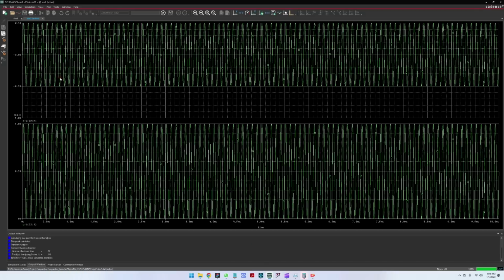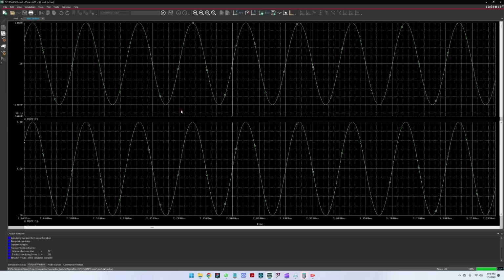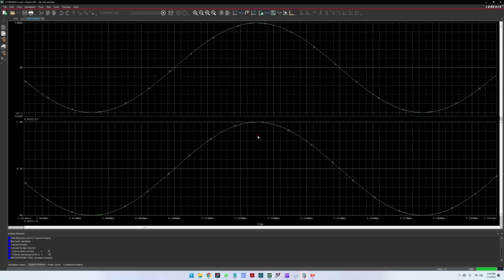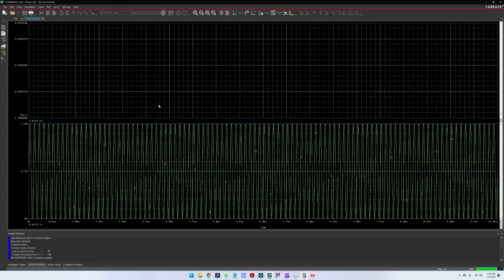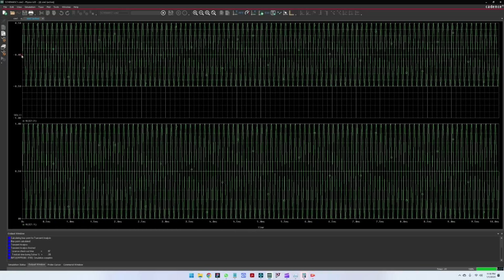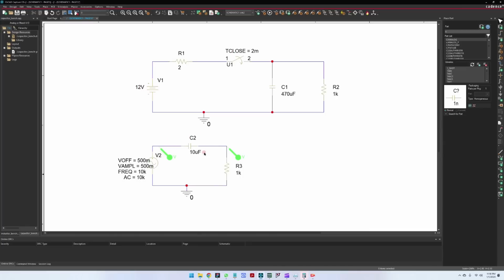So yes, after passing through the capacitor, you can see this beautiful sine wave, and you can also see a dephase between these two, very small. Yeah, it's unnoticeable at this time, but you can see that the same signal passing through these two components. Okay, one is at 0.5 and the other one has no DC component. Why? Because we have this isolation capacitor here.